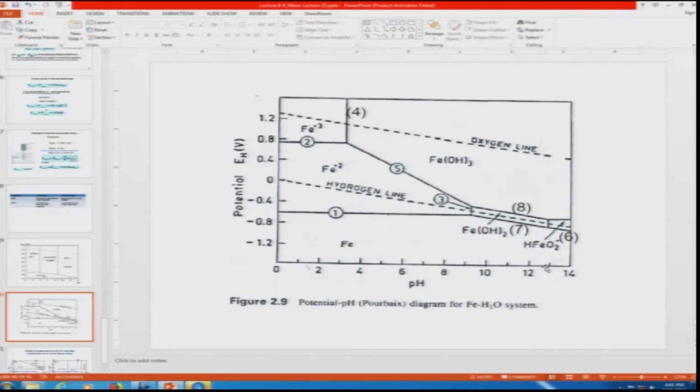So, generally in case of rebar, we maintain the atmosphere, so pH is maintained at around 12 to 12.5. At that high pH the iron passivates within that concrete system, when the rebar is placed in a concrete medium. So, if it passivates, dissolution becomes very limited at 12.5, but 12.5 is not suitable for aluminum, because when we go to 12.5 we might get to the corrosion zone, which is AlO2 minus. So, this information we can definitely gather from the Pourbaix diagram.